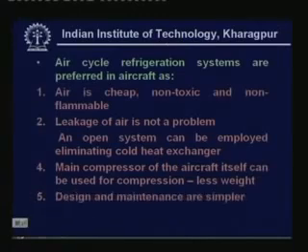So, you will find that weight per kilowatt of an air cycle system will be much lower than a comparable vapor compression system, for example, using a reciprocating compressor. In fact, the calculations show that the weight will be typically 50% that of the comparable vapor compression refrigeration systems. So, these are the reasons why we use air cycle refrigeration systems in aircraft. Of course, the last reason is that the design of these systems is considerably simpler, and the maintenance is also easy. So, these are the reasons why we prefer air cycle systems in aircraft.